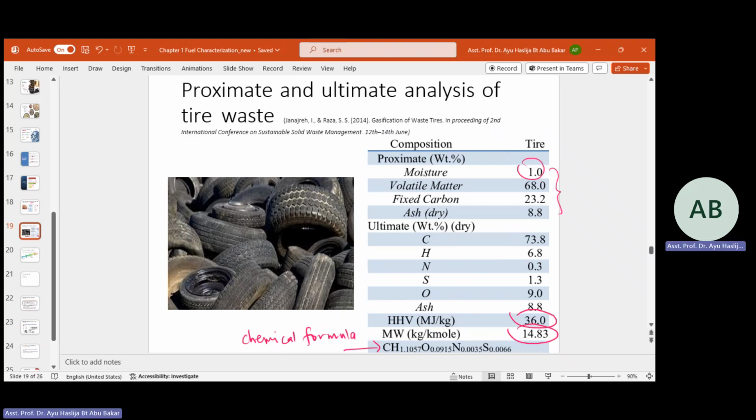I once went to Top Glove in Klang. They had an issue with their boiler combustion chamber. So we did a collaboration research. They were dealing with an air fuel ratio issue. So that's what I suggested to them, to look at the air and fuel ratio. Because basically with combustion, if it's not okay, it's only about the air fuel ratio. If combustion is incomplete, you will have many gases produced. If combustion is complete, you will have fully CO2 and H2O.